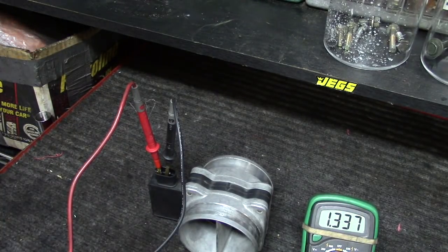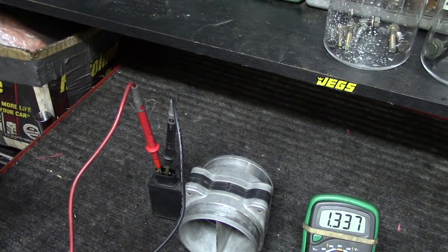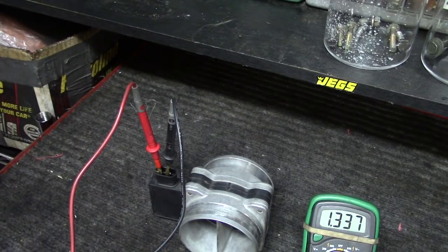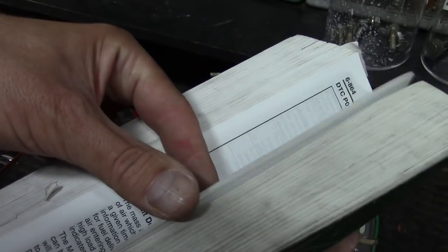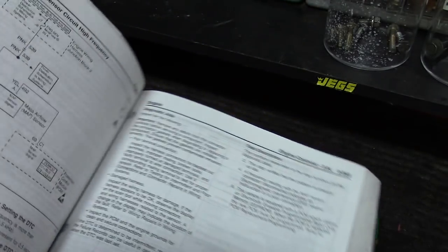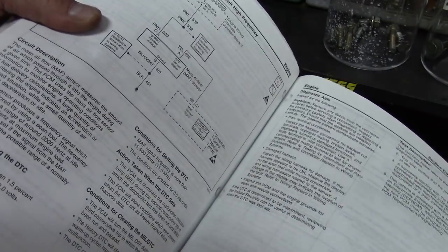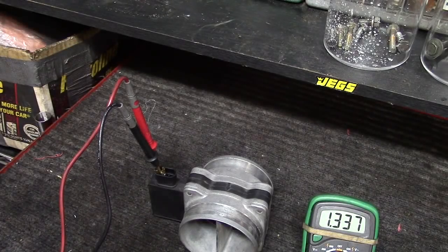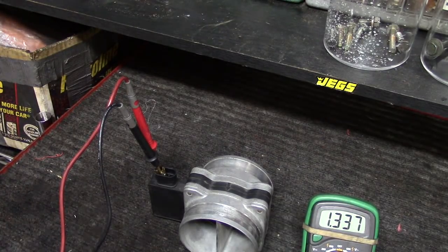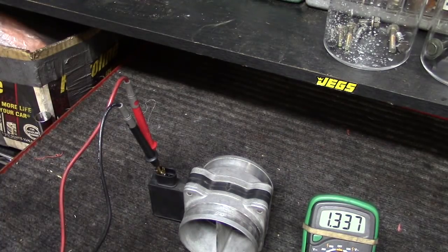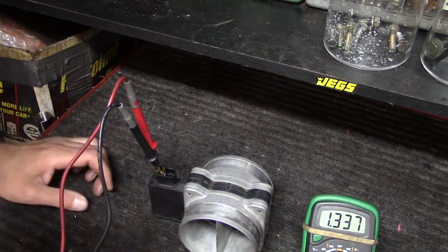Now, there often will be an actual resistance specification as well here. And as a matter of fact, let me go ahead and look up if there is one. In my service manual, there is actually no indication for a resistance in here whatsoever, but there actually are a couple for frequency readings that the PCM would look for instead of DTC. So of course we would have to know those, and then when we do frequency testing on the sensor, that would be a good diagnostic test. But for our continuity test, this would suffice that we clearly have continuity between the power and the ground.